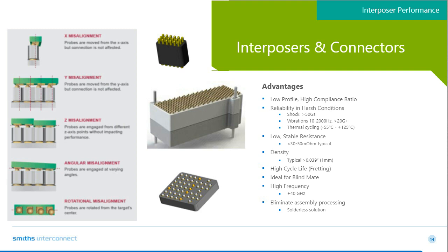When we approach a new design with a customer, it's important for us to understand the details of what the survivable versus the operational needs are from the start to allow us to make sure we provide a probe design and a housing method appropriate for your individual needs. The values here are just a general example of some of our capabilities and completed designs that far exceed these parameters, albeit on a case-by-case basis, is what we've been able to accomplish with other customers. Typical resistance of many of the spring probe designs fall in the 30 to 50 milliohm range.